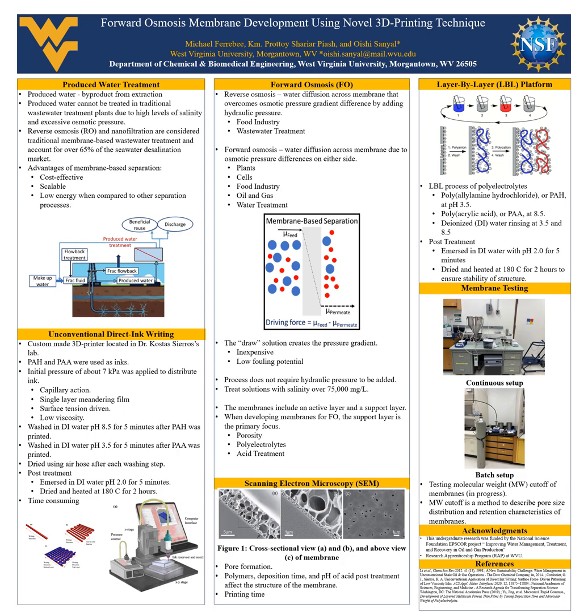The traditional reverse osmosis membranes work by overcoming the pressure gradient formed by the membrane by adding hydraulic pressure to the system to facilitate the separation. This is commonly used in the food industry and wastewater treatment, where the salinity is less than 75,000 milligrams per liter. Forward osmosis membranes facilitate diffusion using the pressure gradient without added hydraulic pressure. This process is found in nature with plant roots and cells and is used in different industries with water treatment over 75,000 milligrams per liter.